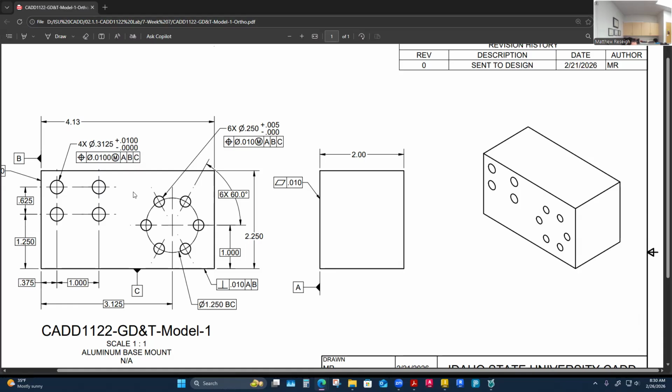And then they can set a level across the two. All they are is these little standoff posts, and I should pull them up. They're called two-hole pins and they're just kind of tapered, anyway, it's a whole thing, but all it does is allow you to set a level across those two holes. So you can quickly throw a level on those and line them up at the 12 o'clock position on a piece of pipe.